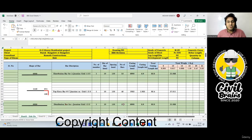So number of bar, how will I find? Very simple. Round up 1,550, this is what I have selected, divide by 150 plus 1, I am supposed to do. Then comma 0, close the bracket. You will get the number of bar, which is 12. And total cutting length is 6,900. And if you put in meter, 6.9. So the answer again remains the same.